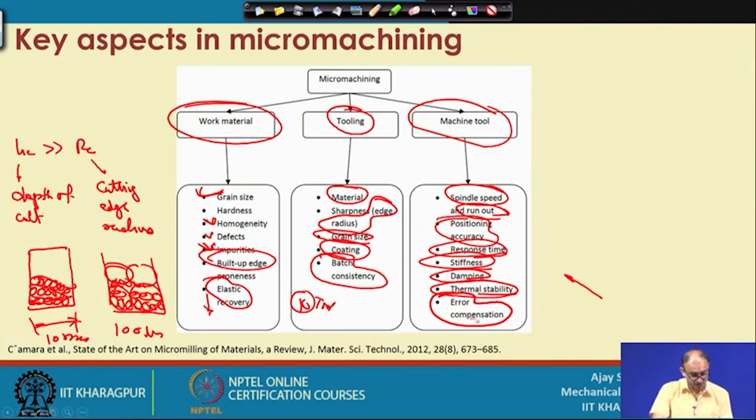If you can calculate the error compensation, then if you are going to target a particular location where your tool is located, what is going to happen is that once the temperature is different at different parts, your machine's temperature sensor will calculate those temperature differences, and those differences will be transferred into the motion controller, and the motion controller will again target this particular part to the actual location. So, at that time, error compensation is related to temperature compensation.